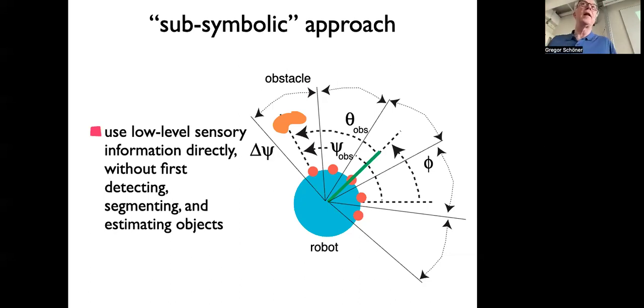So if very little light comes back, there is no surface within the maximum range of this sort of sensing, which was very close, like one vehicle size. You would no longer get a useful signal back. If there's some surface within this cone in which this light beam was focused, you would get a signal back. And the closer that surface, the more signal you would get back.